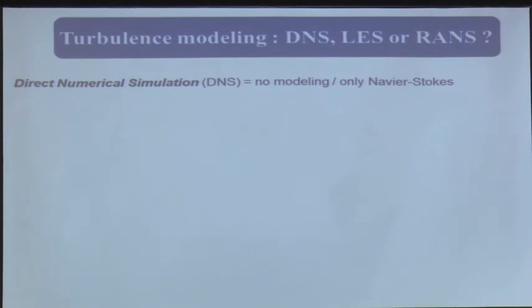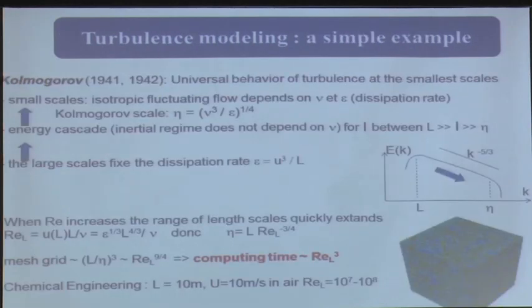You just take the Navier-Stokes equations and do the applied mathematics job by discretizing the equation with finite element method, finite difference, or spectral, any method, but you solve the equation as exactly as possible with the scheme you selected. You don't modify the model. But this is going to give you a limitation.